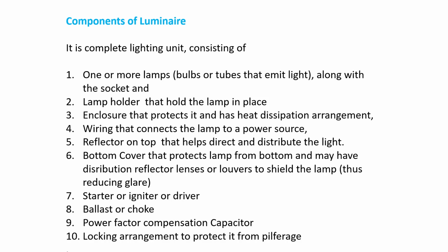Sixth, the bottom cover that protects the lamp from the bottom and may have distribution reflector lenses or louvers to shield the lamp, thus reducing the glare. This bottom cover is also known as Perspex cover. Perspex is a brand name. Seventh, starter or igniter or driver. In case of LED fitting, it is a driver. In case of sodium vapor fitting, it is an igniter. And in case of fluorescent tube, it is a starter.